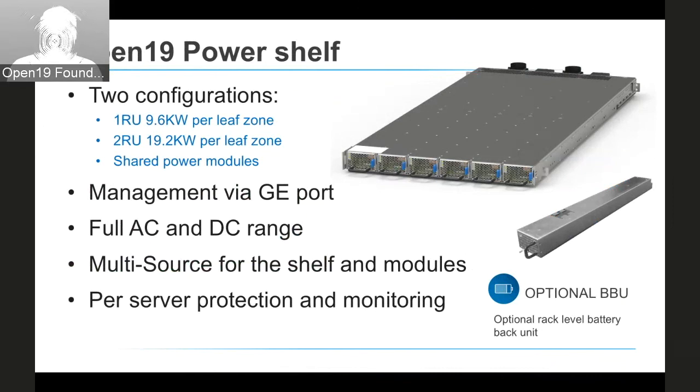Another element, two or more elements that I would like to emphasize about this PowerShelf. This PowerShelf is unique from a perspective that it's actually isolating every server in the rack to have separate protection and monitoring. Every element in the rack has separate eFuses which protect it from shorts or any faults, and even if a fault happens, there is no relationship between the servers. Each one of them is independent.